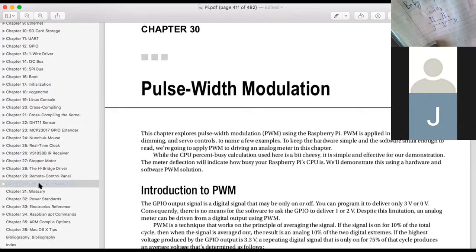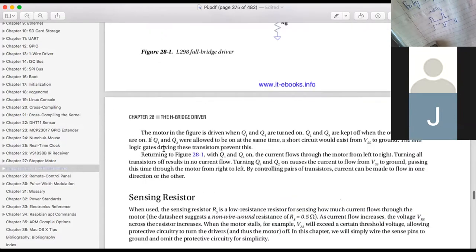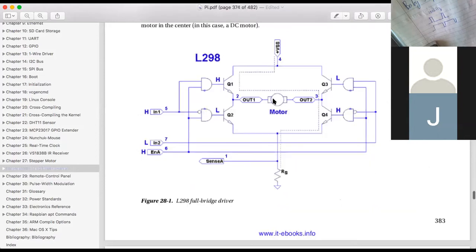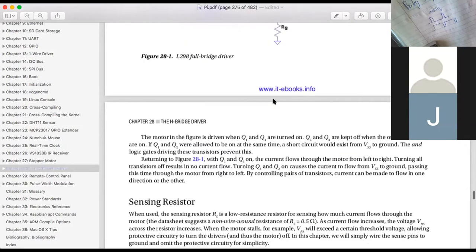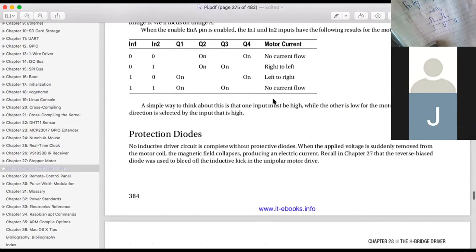You do it tens of thousands, hundreds of thousands of times every second. That will smooth out and become a varying RPM. So this is an H drive, and using an H drive to control a DC motor, you can control the RPM of the DC motor. That's very commonly used for control.